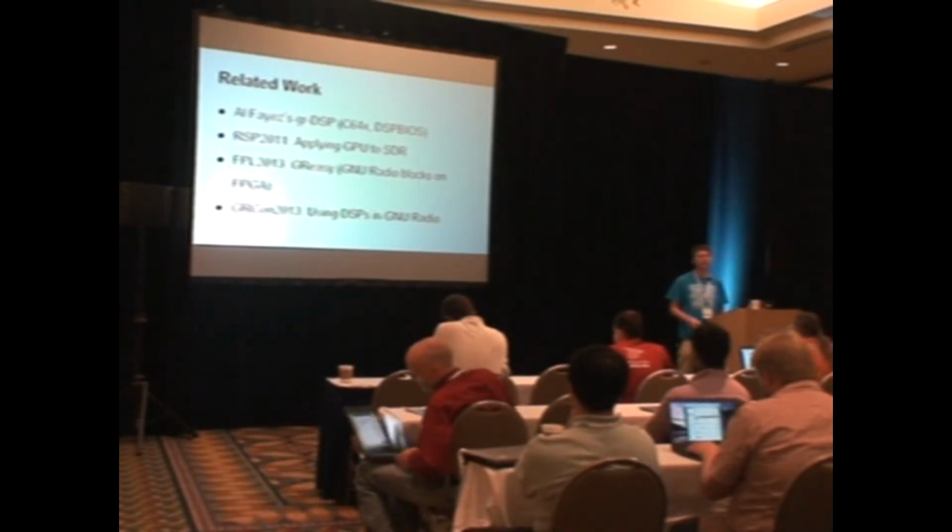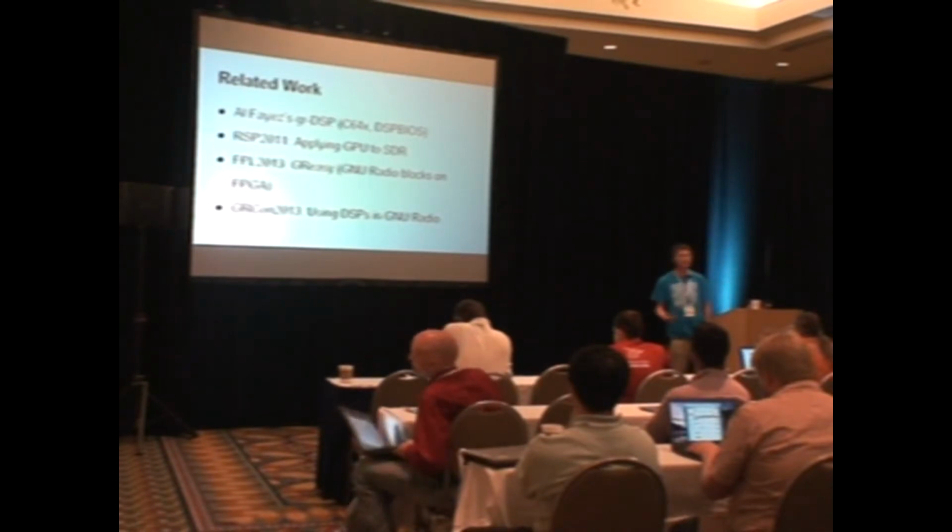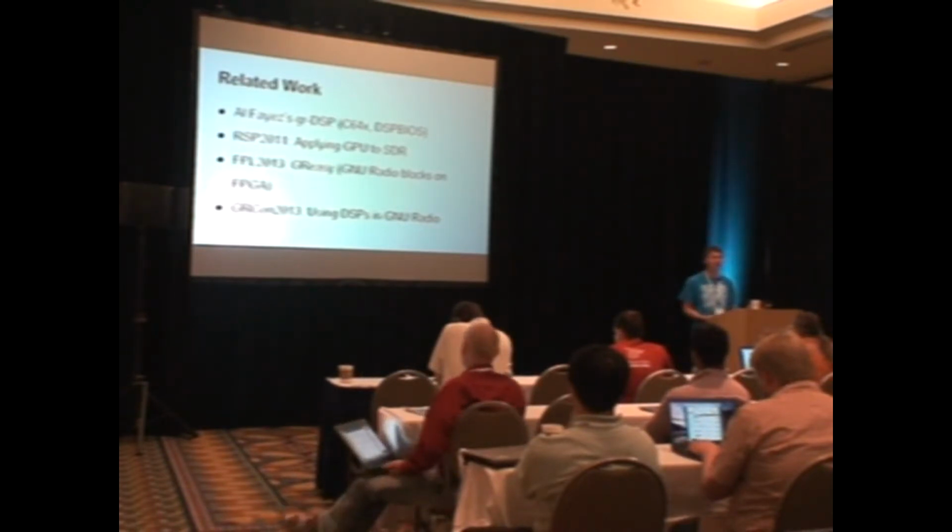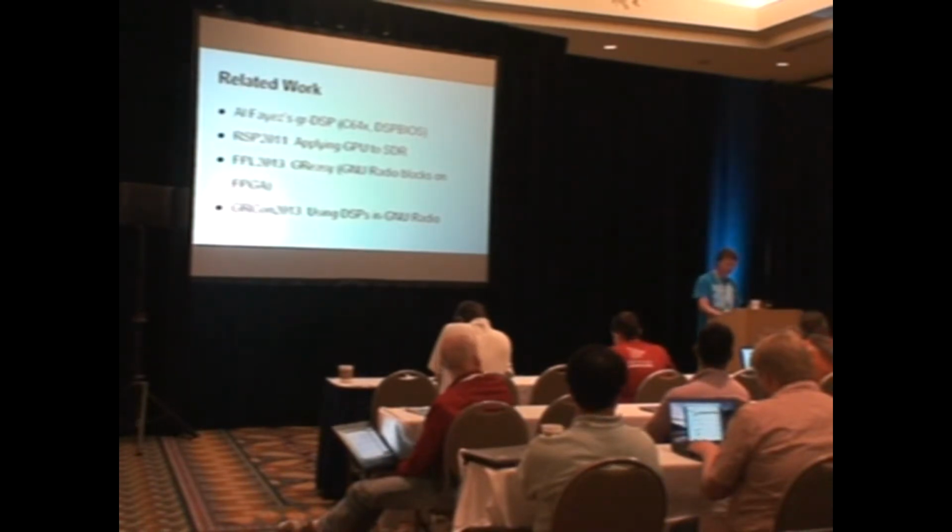We don't want to lock ourselves in to any one coprocessor solution. We need to get to where we basically have GNU Radio dealing with whatever clever ideas the silicon guys come up with. Keystone 2, one chip. Yes, those coprocessors, basically on that chip. Now there's a PCI interface that you can hang an FPGA off of and then have the ultimate solution.